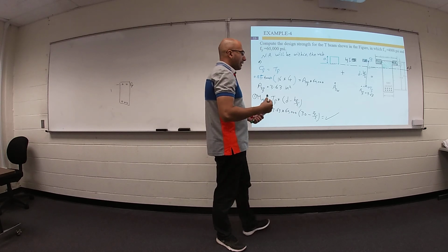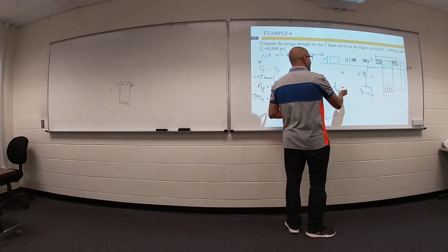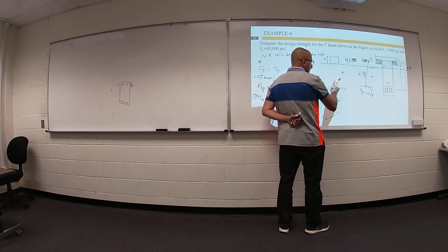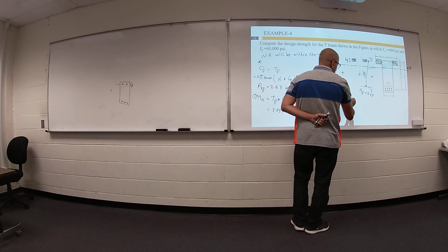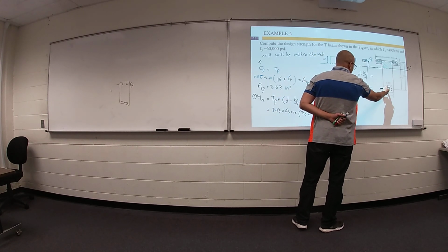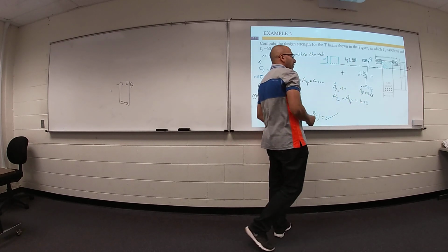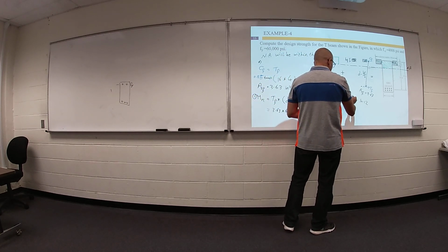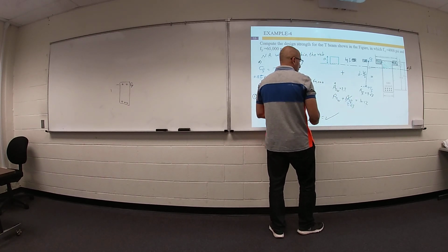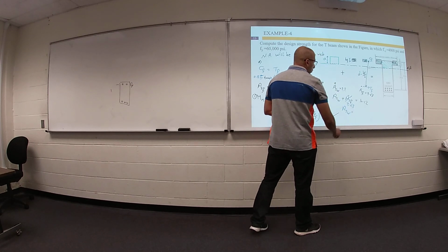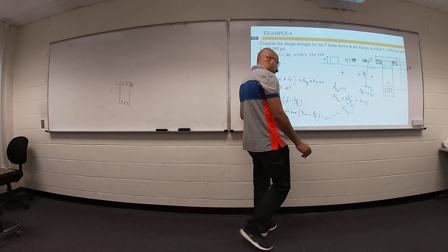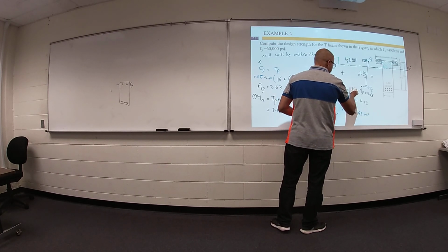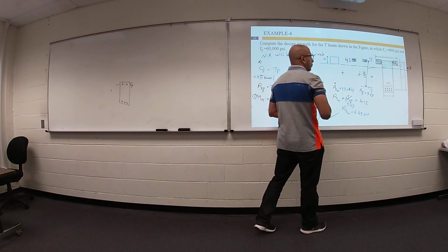For the second part, anybody can tell me what is the area steel web? Yeah, area steel web for this part plus area steel flange for this part equals the original area of steel. From the first part, you can figure out the area steel flange, 3.63. So I can figure out the value of area steel web. What is the value? 6.49. 6.49 inches square.